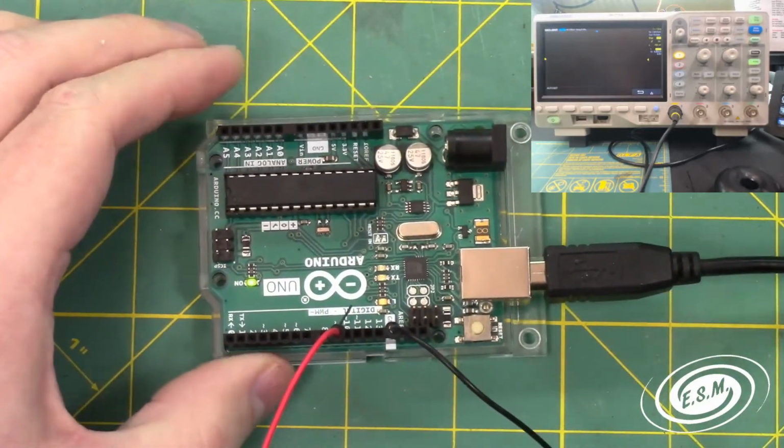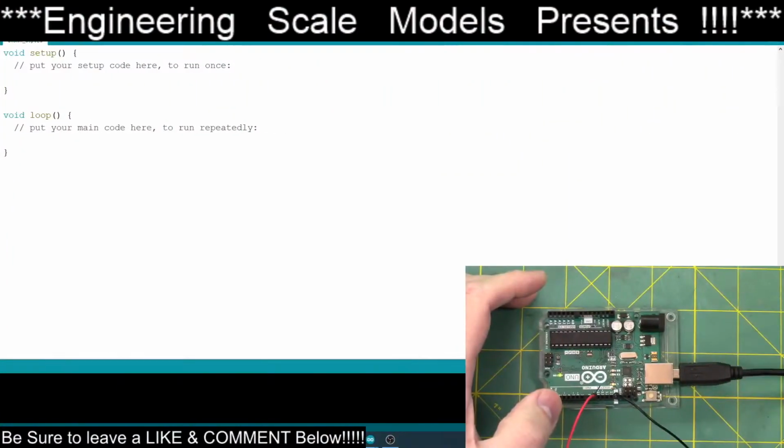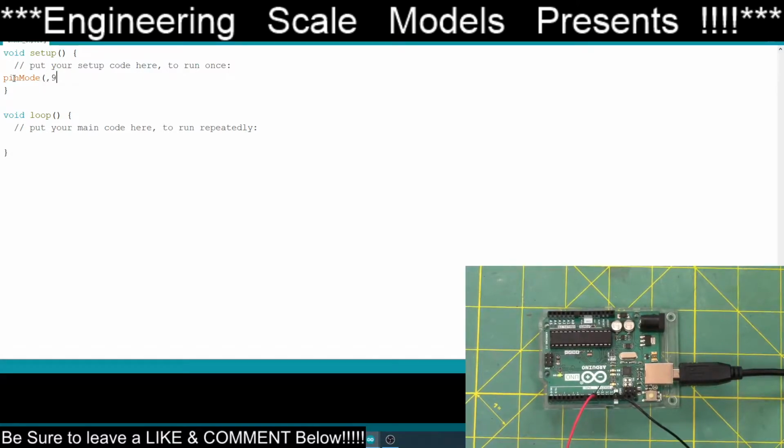Now I just need to swap over and write some code here. We're going to write a quick code. We are not even going to do the important stuff of setting the values of the pin. We know it's pin 9, so we're going to do pinMode, pin 9 is going to be an output. We're just going to declare that there.